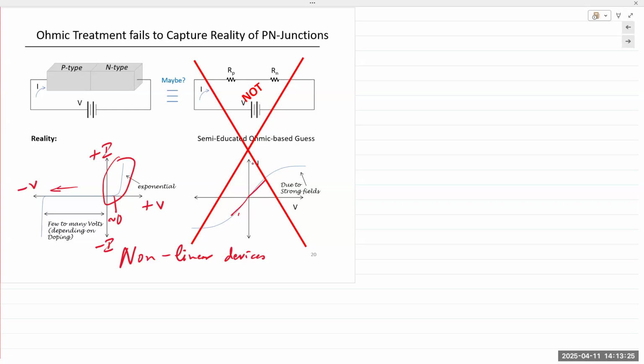Then after a certain point, the voltage crossed a higher limit and the junction breaks down, and there's a huge increase in the amount of current flowing, with a near vertical slope, or near vertical characteristics. Meaning the voltage could increase a very tiny fraction and the current would just increase beyond exponential. That's what they discovered.